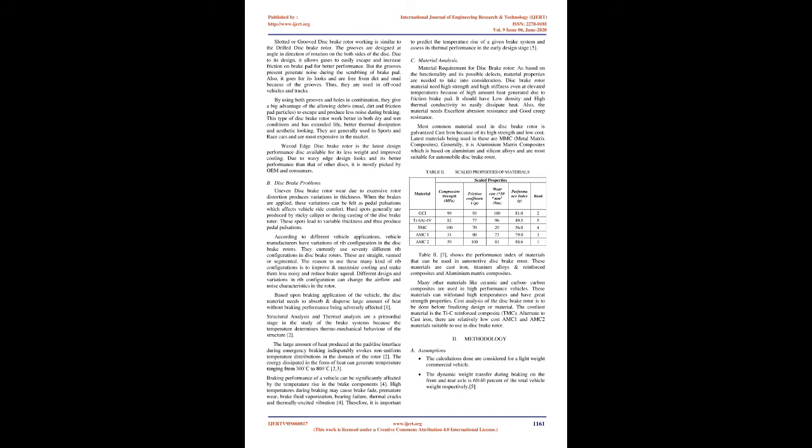Slotted or grooved disc brake rotor working is similar to the drilled disc brake rotor. The grooves are designed at an angle and direction of rotation on both sides of the disc. Due to its design, it allows gases to easily escape and increases friction on the brake pad for better performance. But the grooves present generate noise during the scrubbing of the brake pad. Also, it is used for its looks and is free from dirt and mud because of the grooves. Thus, they are used in off-road vehicles and trucks.